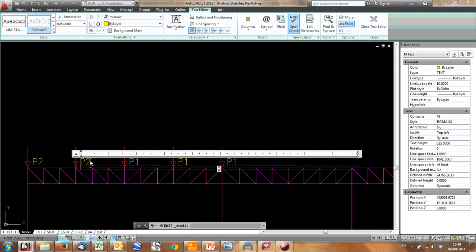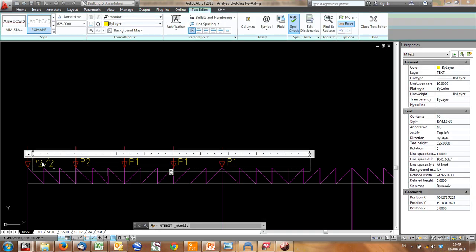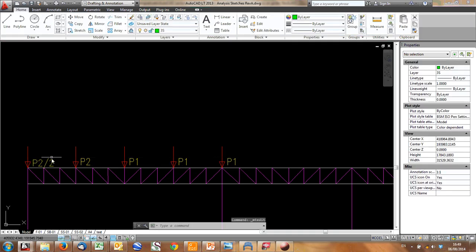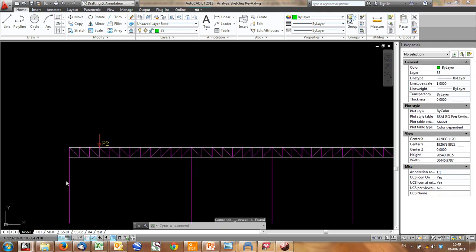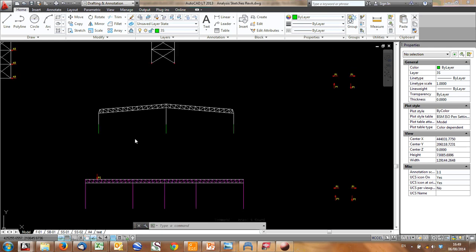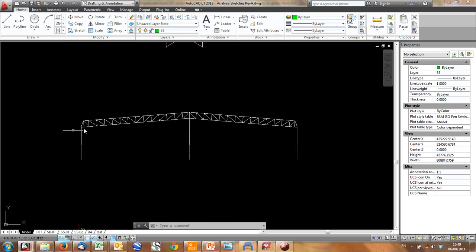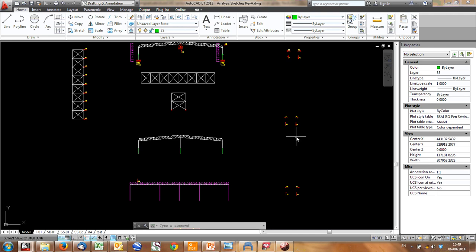The end one would often be P2 over 2 if you halve it, or if it's a rafter, it would be even less than that. But we'll come back and have a look at this force and calculate that, but all the rest of these will obviously be P2. The reactions though, now what horizontal forces would be applied to this? Because we've applied wind load naught, our load combination when wind comes across the structure.